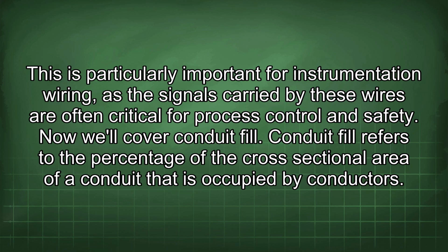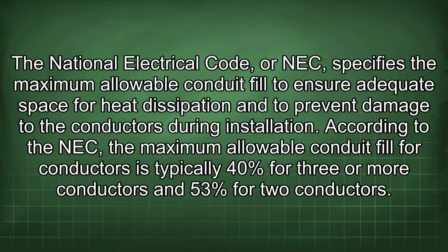Conduit fill refers to the percentage of the cross-sectional area of a conduit that is occupied by conductors. The National Electrical Code, or NEC, specifies the maximum allowable conduit fill to ensure adequate space for heat dissipation and to prevent damage to the conductors during installation.